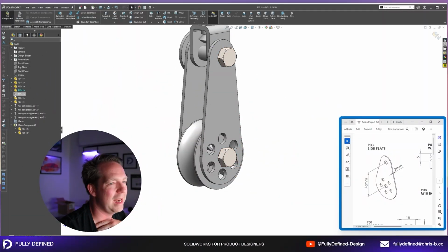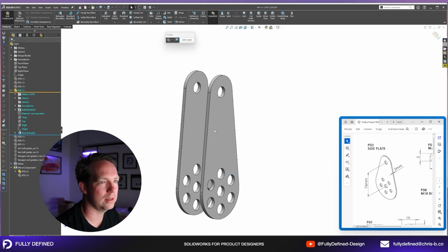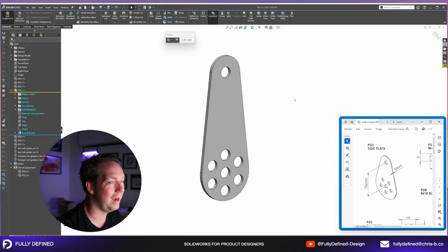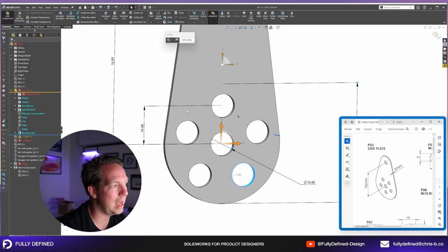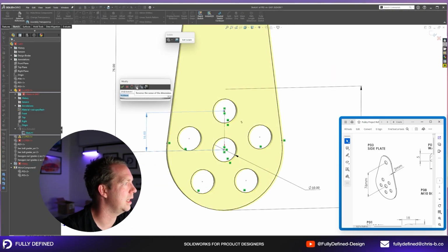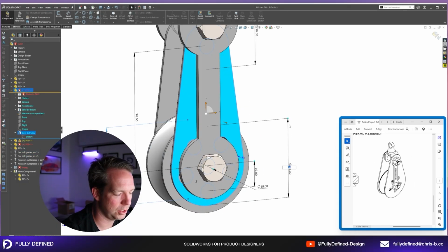The third big theme was not understanding how relationships worked inside SolidWorks, both at the feature level and in assemblies. I used to design everything in context, directly inside assemblies. It felt efficient until I moved parts around, restructured an assembly, or tried to use a component in a different project. Then everything broke. I'd sit there wondering why half my model had errors, with little idea what I'd done wrong.